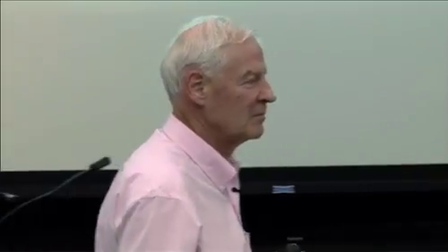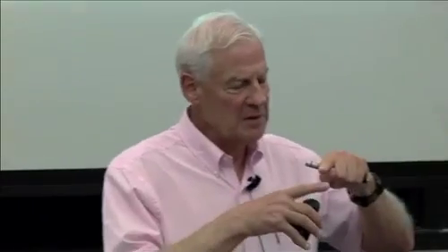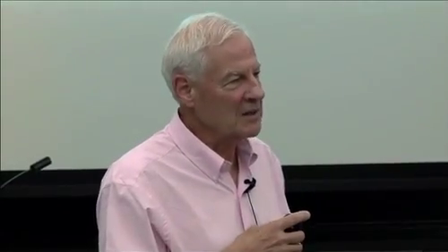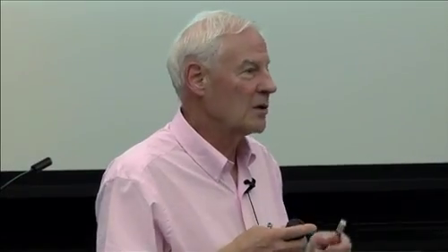So what about the dynamic range? If the concentration changes quite a bit within the experiment. Good. What about dynamic range? The nice thing about absorption is, I told you the minimum percentage absorption we can usually detect is, say, 0.1% in a shock tube experiment. And we don't like it to be more than, say, 60. So the dynamic range is 600. If you say, no, I want it to be 100 times more sensitive, I've got to go to a 100 times stronger line. Too sensitive, I go to a weaker line. Oh, but I want to cover all the range. Then I use 2 lines. So there are potential solutions to these problems. It's pretty hard to find an instrument that works over, say, 3 orders of magnitude. But we can get close with 1 line.